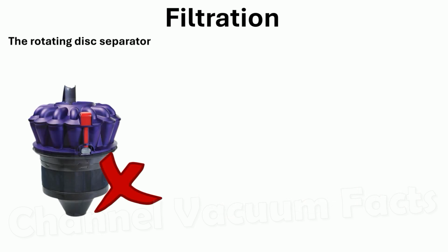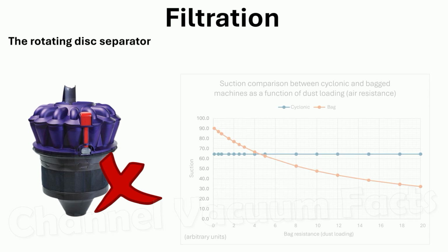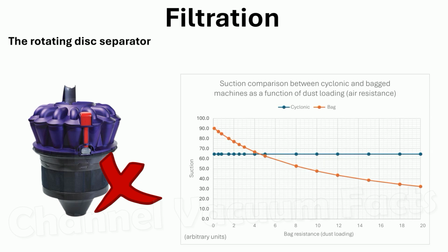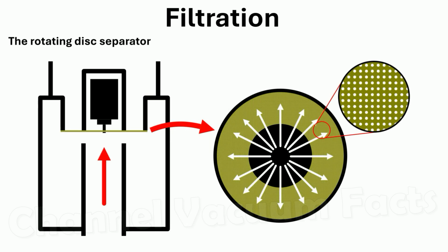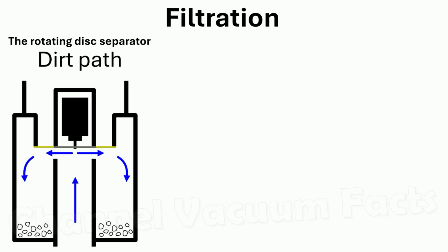Longer term, all cyclones may be eliminated, resulting in substantial energy savings whilst keeping separation efficiency independent of dust loading and the other advantages of a mechanical separation. This may be achieved by using a rapidly rotating disc with a porous mesh. Dirt-laden air entering the bin strikes the rotating disc, is given angular momentum by its rotation, and dirt is centrifugally flung out into the bin.